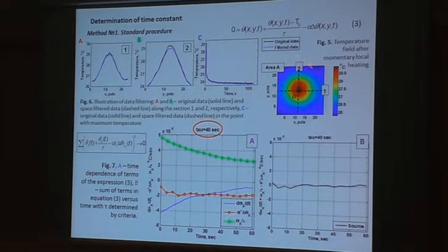One of the standard ways for people who work in thermography is to use a special heat source, like a point which can be introduced by laser or, for example, simply by a soldering tool. And then we consider the heat distribution in the sample without any heat sources, and we find the best constant tau, which gives us zero heat sources in the sample.